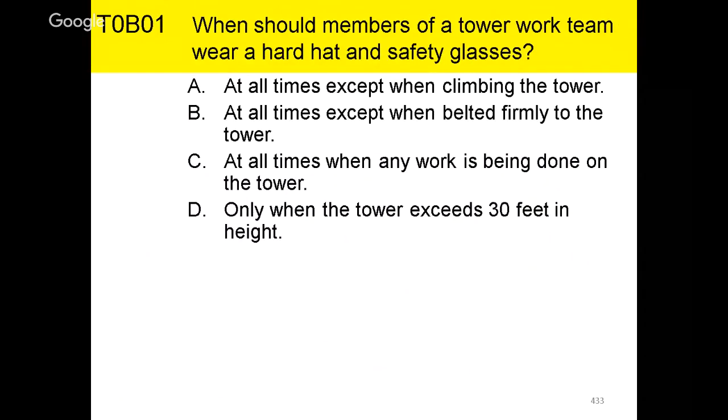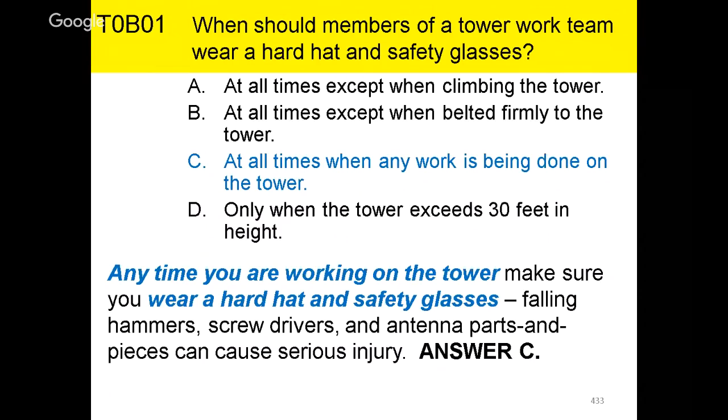When should members of a tower work team wear a hard hat and safety glasses? Well, this should be a no-brainer. Your answer on this is C, at all times when any work is being done on the tower. So you want to make sure that everyone's wearing hard hats and safety glasses, and to watch out for falling hammers, screwdrivers, antenna parts, and other things that can cause injury.